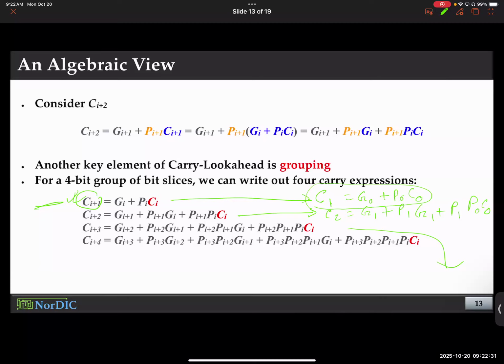Inputs, right? Okay. And notice all of this carry will have C0 as an input. And C0, you don't have to wait on C0. It's the first carry. You just feed it in. How about G0 and P0? Notice the only thing that was slow, by the way, that you were waiting on was carry. But remember what is G? Generate was A XOR B.